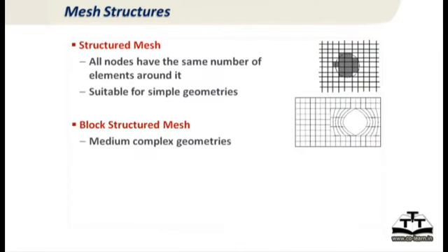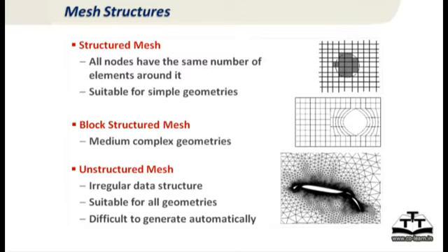So when you divide the component into the elements, the question is whether it is a structured mesh or an unstructured mesh. Structured essentially means a fixed grid or a uniform grid. Unstructured means you can put a smaller element where you need higher accuracy, and a bigger element outside, like at the mold walls, where you don't really need high accuracy or heat transfer is not much. By doing this, small elements in critical areas and big elements in outer areas, we can reduce the computation time.